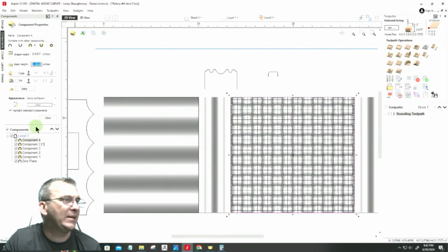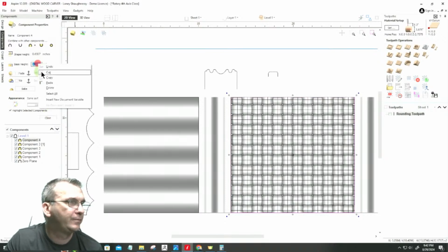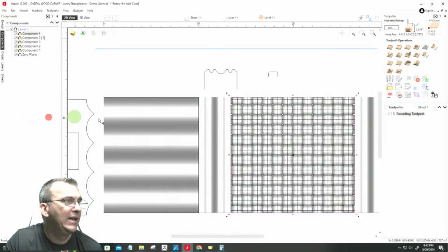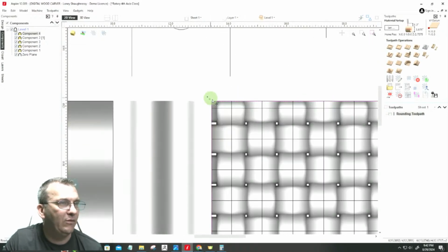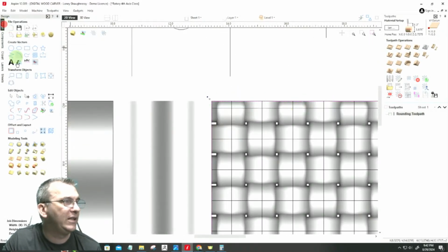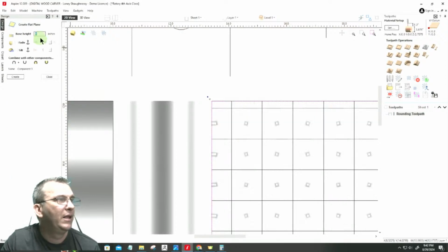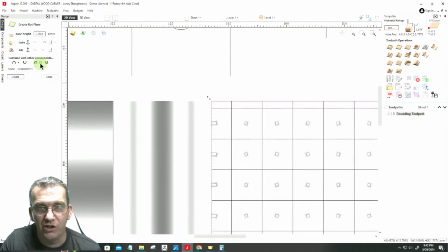Well, in this case, I'm going to make it simple. I'm going to copy this base height value here, go back and select my rectangle, go into the design and create a flat shape that tall. Paste. Now that shape is going to merge with the rest of my model.